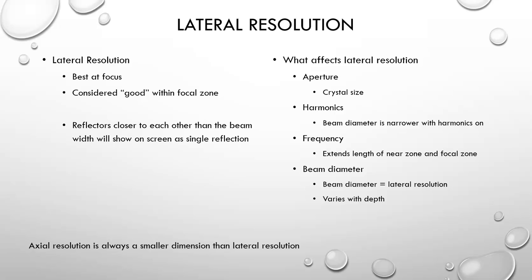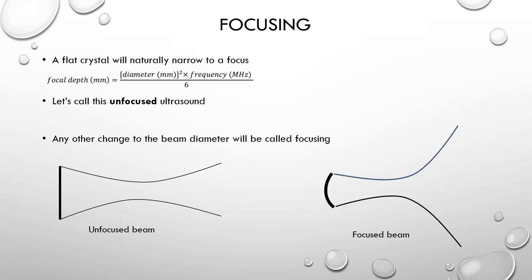As I said, focusing is very important for lateral resolution, and so focusing is something we need to discuss. A flat crystal or an unfocused crystal will naturally narrow down to a focus. And this is given by that equation I gave you. Focal depth is equal to the diameter squared times the frequency divided by 6. We call this unfocused ultrasound.